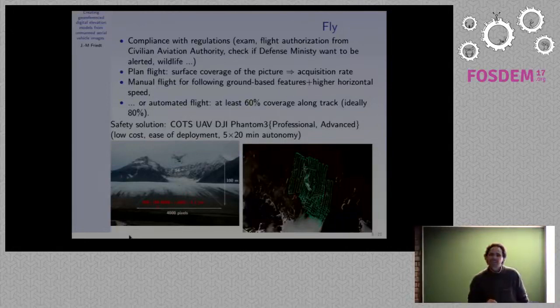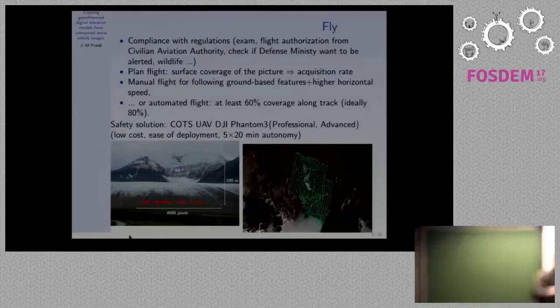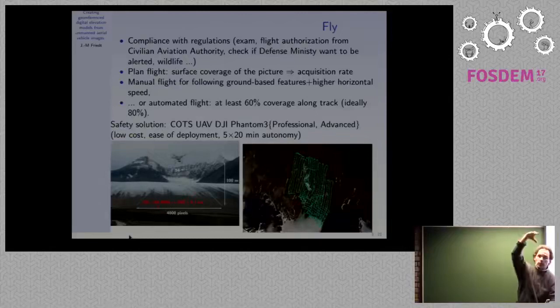But how does the software calculate the difference in height? It will see these various tie points. The SIFT algorithm has a scaling invariance property, so even if you change the altitude, the software will still be able to find relevant tie points and compute what the altitude was.